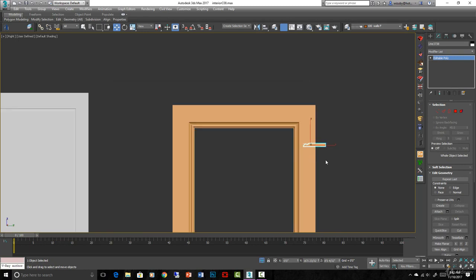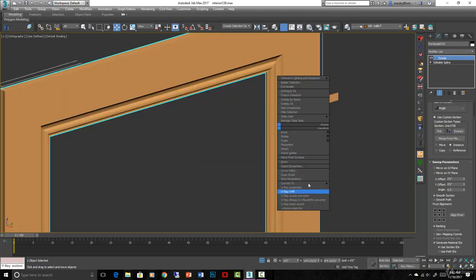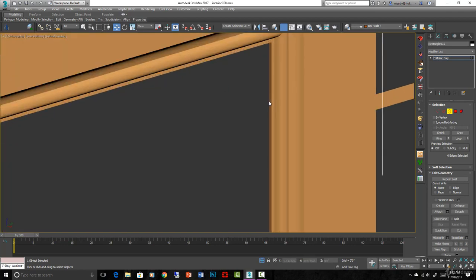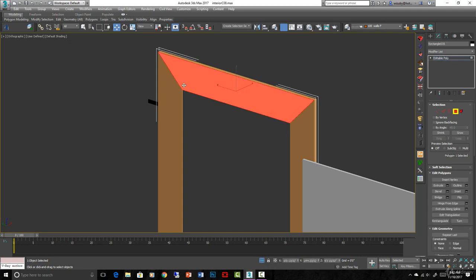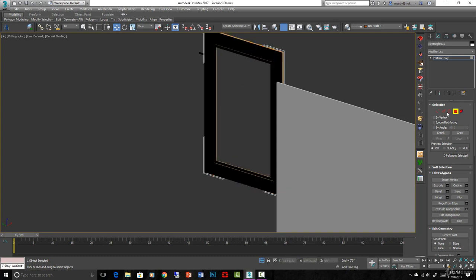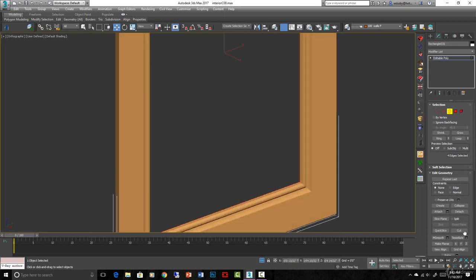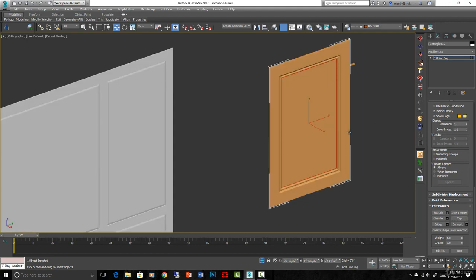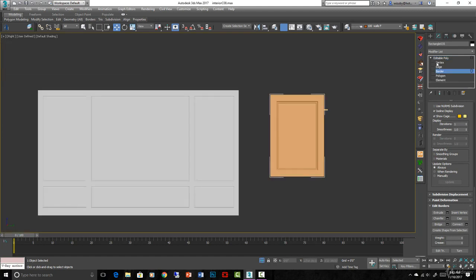Okay, once you have your spline and your sweep made, sweep is just a modifier obviously, but let's convert that to edit poly. Now we can take the borders, and actually we made it a closed object, so there are no borders. But if we delete these back faces, then we will have a border right here. Borders have to be open, and we will cap it like that. Of course, you could have just made another rectangle and attached it to that poly. I do want it to be all one edit poly because then I can stretch it all together.